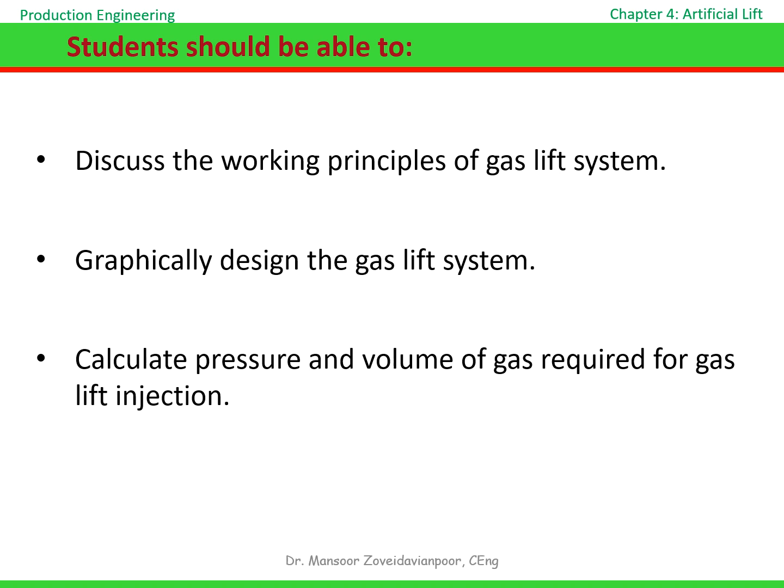This is the practical engineering part. A gas lift system is only effective if we inject the right amount of gas at the right pressure. Too little gas gives poor lifting performance, while too much gas wastes energy and can even reduce production. By the end of this chapter, you should not only know what gas lift is, but also be able to design and evaluate a gas lift system from an engineering perspective. Now let's start with the fundamentals and look at how gas lift actually works inside the well.